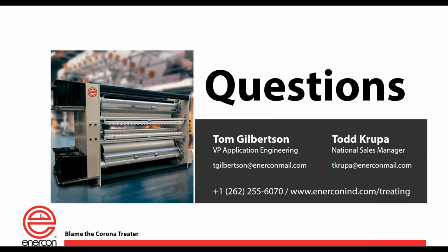First question is, how much moisture is excessive moisture when it comes to corona treating? Well, that's a great question. I've never had anybody, this is Tom, I've never had anybody ask me that question before. Let me just put it to you this way. If you have condensation, or you can actually see moisture on the treater roll, on the web, in the electrode assembly, things of that nature, or concurrently, if in that condition you're seeing high voltage arcing where the treater's not staying on, it'll arc to that water, that would be way too much, right? So you want to make sure certainly nothing's visible.